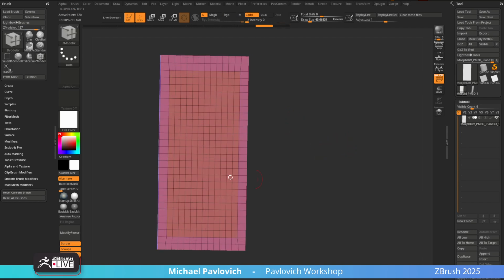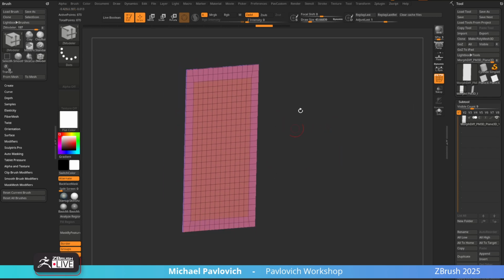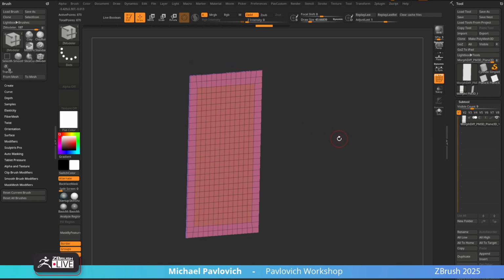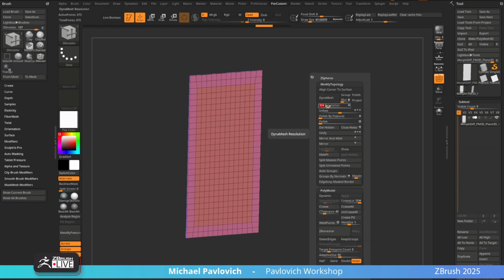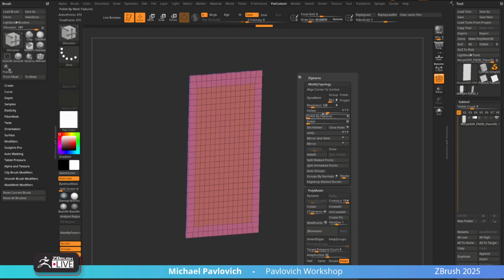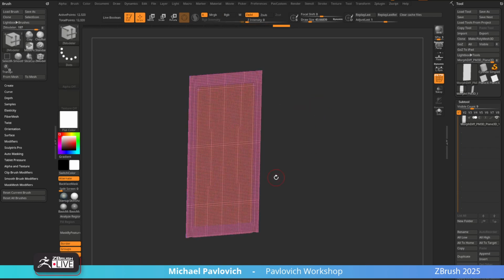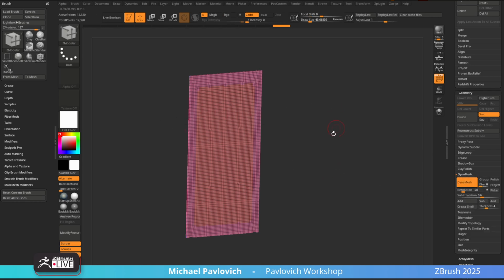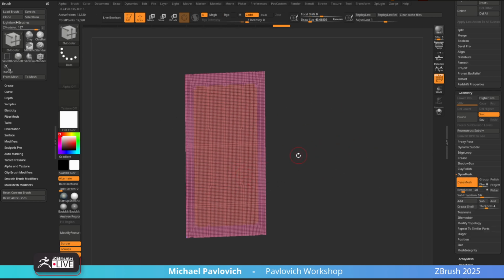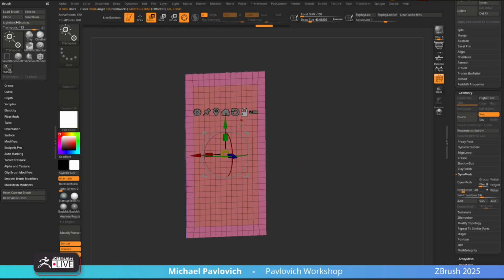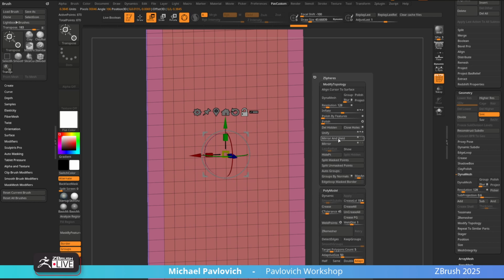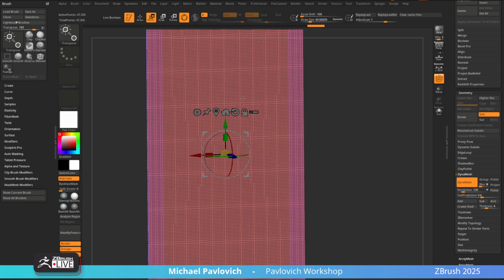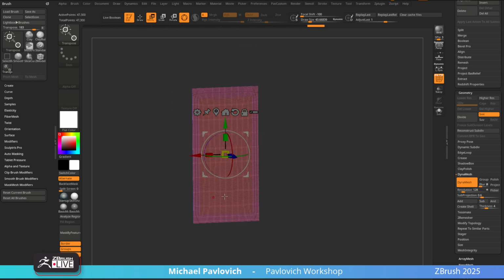That's a little weird. Dynamesh is kind of scale based. So for instance, let's keep it at 128. I want a Dynamesh at 128 here. So I Dynamesh. For everyone else, Dynamesh is under Geometry. Dynamesh basically just turns your mesh into clay. But if I scale this way up and then say Dynamesh at 128, it's still the same resolution. It's just packed more in there.